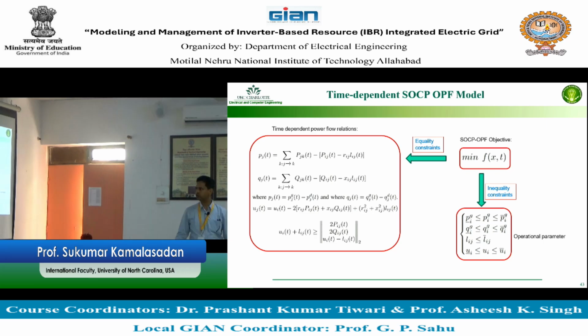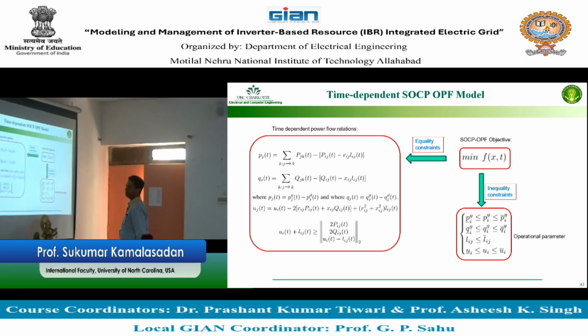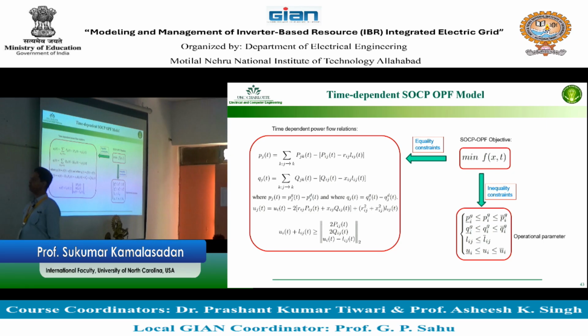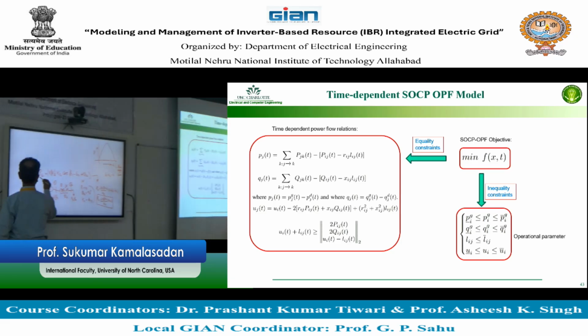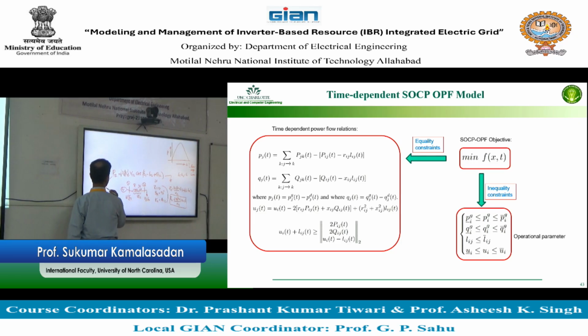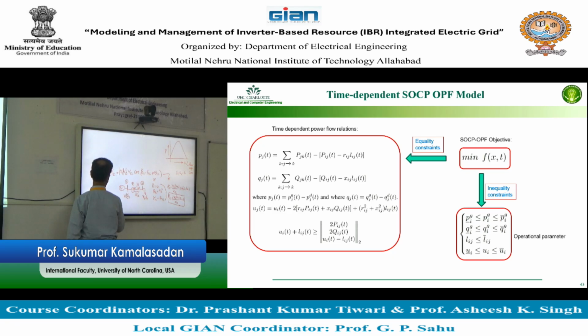Good. So, what are we doing by running the power flow? We are trying to find this P12. I want that P12 to go to P12 star, which is the value I want. The difference between them is called delta P12.